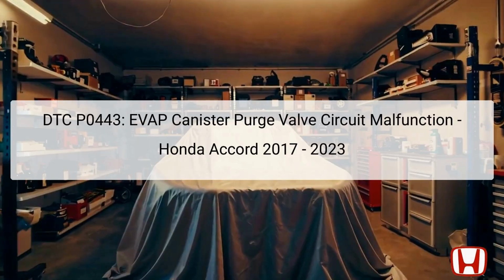Diagnostic Trouble Code DTC P0443 indicates an issue with the EVAP Canister Purge valve circuit. The EVAP, Evaporative Emission Control System, purges fuel vapors from the charcoal canister into the intake manifold, helping to reduce harmful emissions. Specifically, this DTC points to a malfunctioning circuit related to the purge valve, which may be either stuck open or closed. This malfunction can affect vehicle emissions and performance, making it crucial to address.